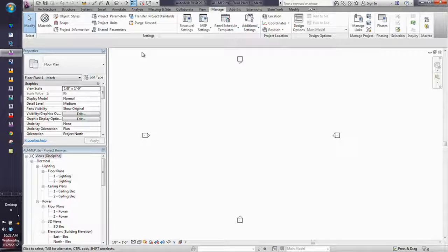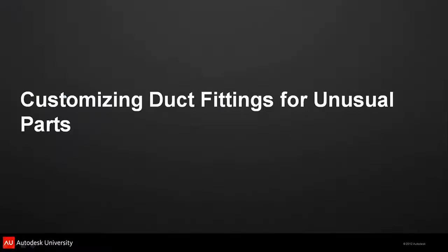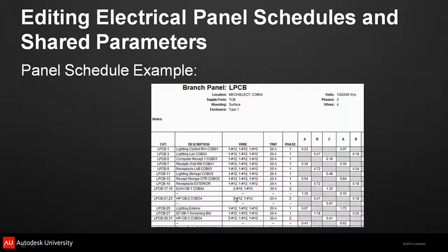Then when I go into a project and I start to assign electrical equipment, what I'm going to get in the schedule is what you saw in that PowerPoint. That's what will make this show up as 2 wires. When you use that wire type on a piece of electrical equipment, then it will only show the 2 primary wires in here, the 2 wire types in here. Okay?